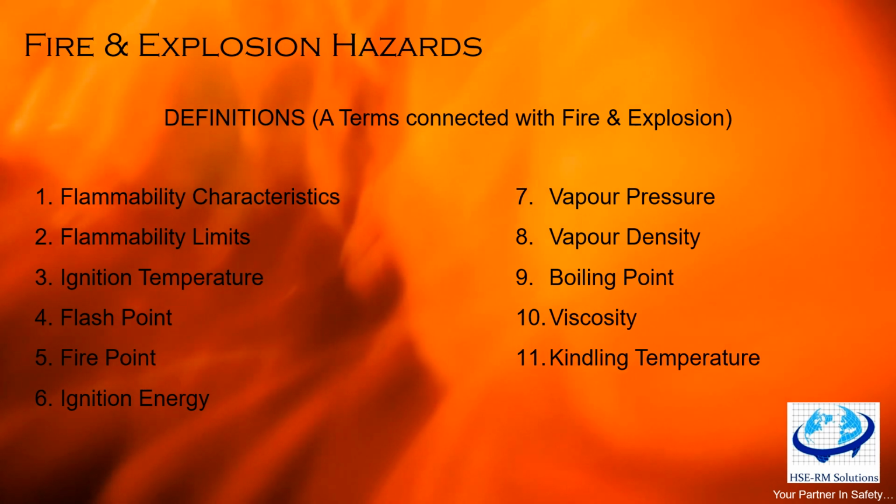The auto ignition temperature may be reduced by as much as 100 to 200 degrees Celsius for surfaces which are lagged or contaminated by dust.